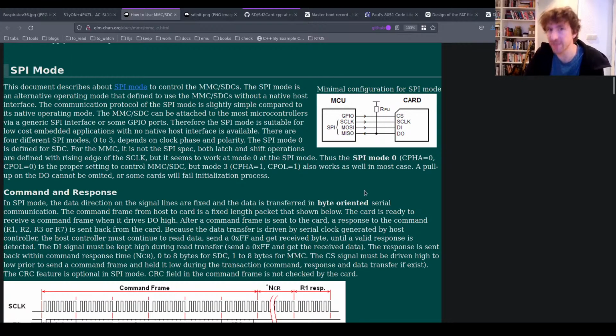And if you did a pull-down resistor, you're going to ground. You put a resistor going to ground, you pull the line down to ground in the absence of a real signal. And because of the choice of resistor that you use, this is just an electrical thing, you can think of the signal line as favoring an actual signal going across rather than the pull down to ground or the pull up to 3 volts.